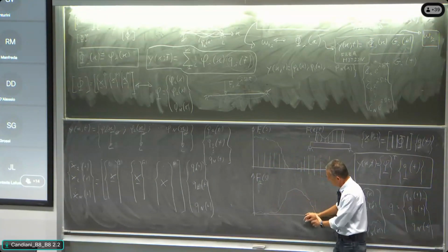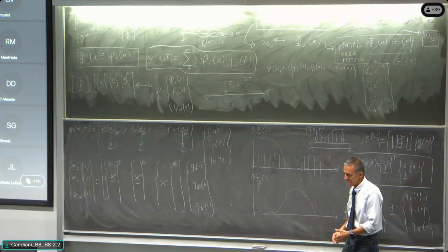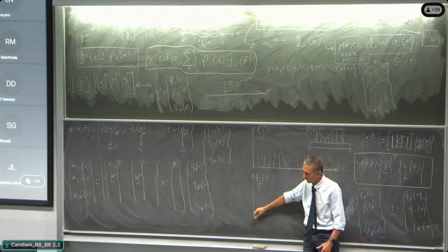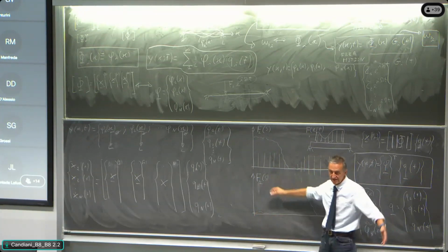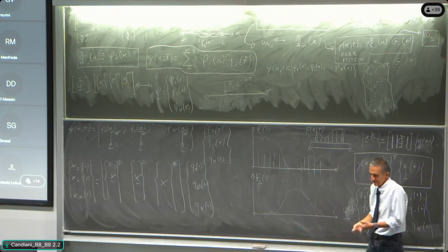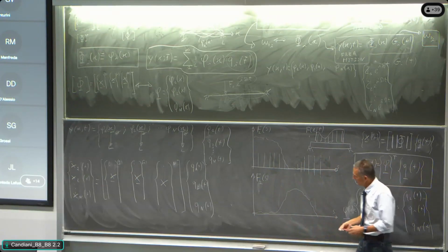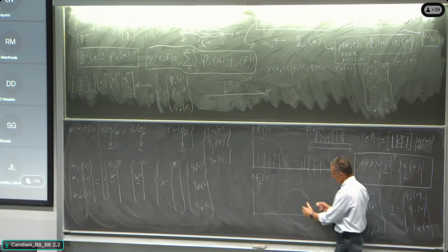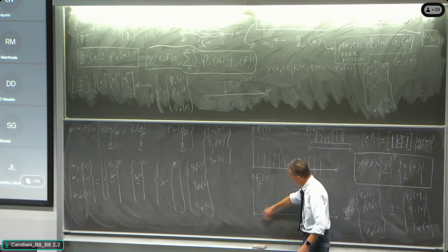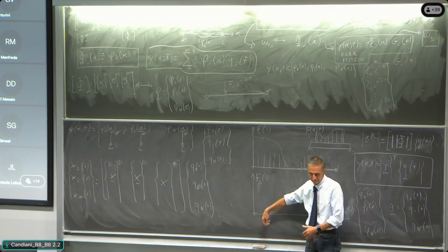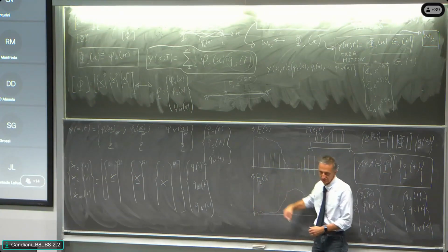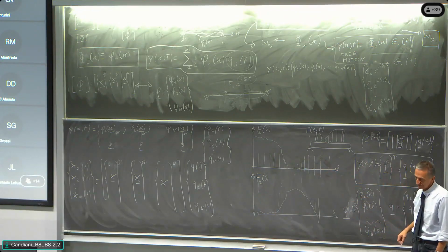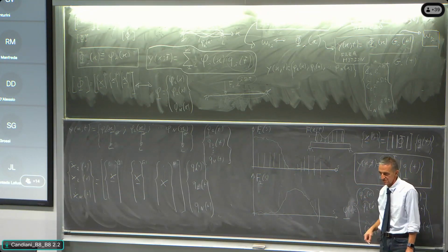In a situation like that, if I want to represent the dynamics of the system, and the bandwidth of the excitation is here, and in the low frequency there is almost nothing, it is interesting, maybe, to limit the number of modes with which we are playing, and to consider just those, forgetting the first 1, 2, 3, whatever, and then forgetting the ones that are over the maximum frequency of the spectrum of the excitation, all right?